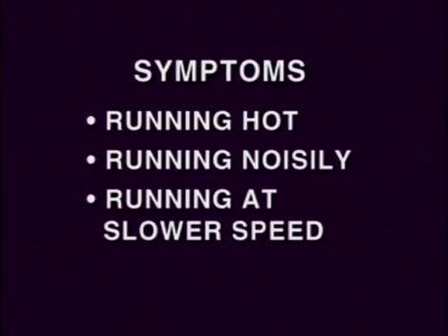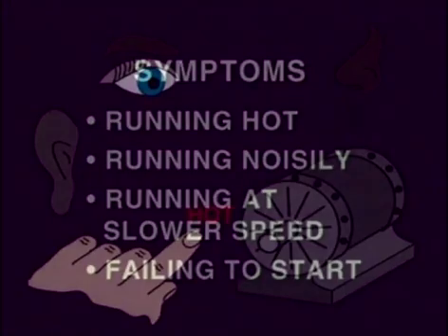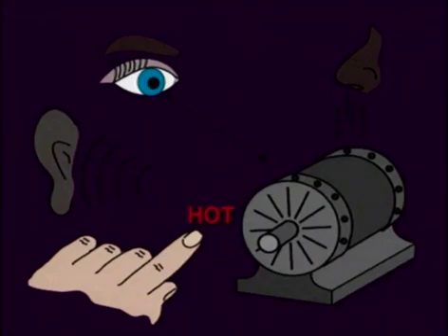These are the matters we must anticipate before these conditions get to our motors. Most often, motor problems give symptoms of abnormal operation, such as running very hot, running noisily, or at a slower speed than normal, and even failing to start. Each of these symptoms will tell us that the motor is not operating properly and that we must pay attention before long. We need to use our sense of smell, touch, hearing, and feeling at all times in order to detect some of these problems.